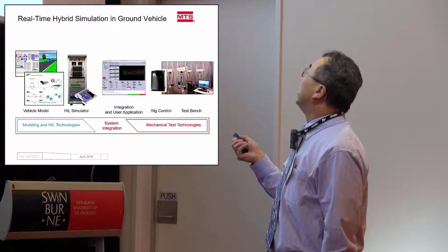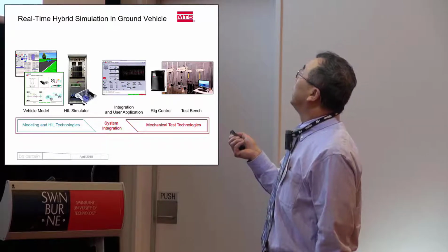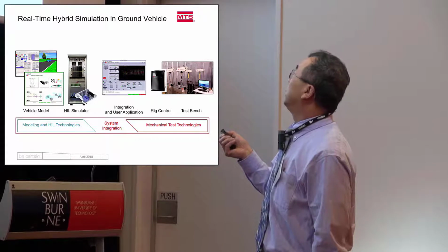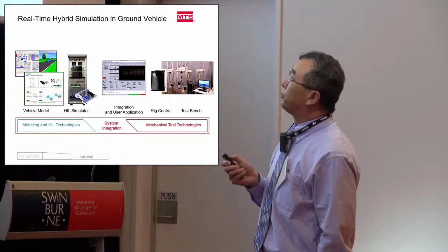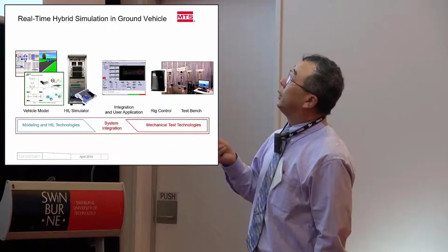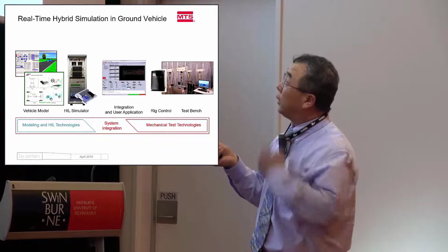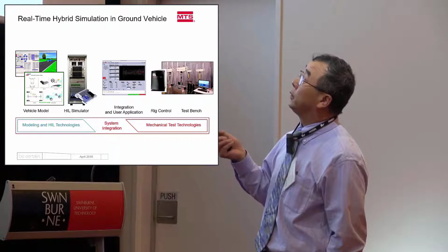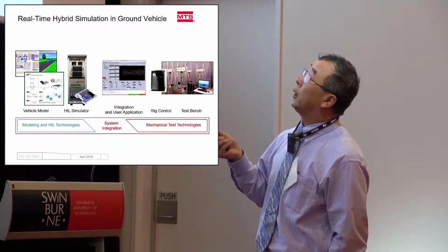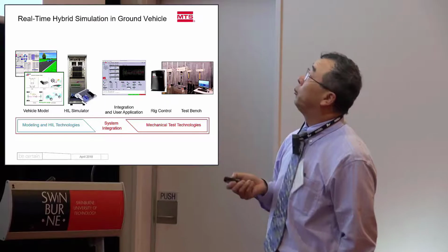The numerical substructures are the road, tire, and the car except those dampers. And the physical substructures are those dampers. So the model is run in this HIL simulator display system, and CarSim is the software to simulate the car driving on the road, with all those 4 dampers.